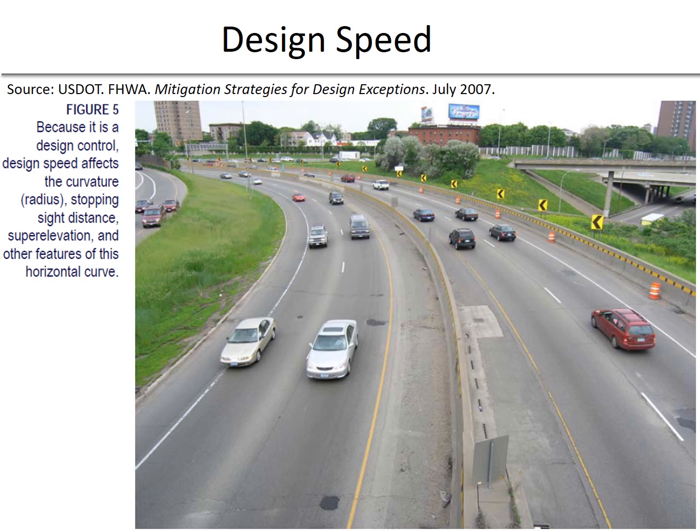There's a difference between the designated design speed, and that's what we've been talking about, where we have a selected speed that's used to determine various geometric features of the roadway, and then the actual inferred design speed and the operating speeds of drivers. So as a driver drives along a roadway, they're going to infer a design speed and start to understand the characteristics of the road and what speed is a safe speed for them to operate at.